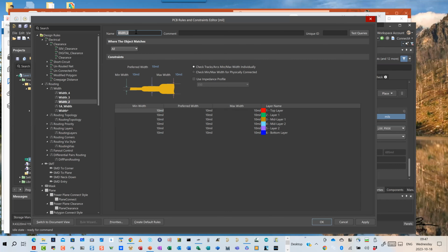That's what I'm going to do here. Now, you'll see this when you go through the groups. There is actually a 5 amp class in there that I created. This one's going to be my net class 5 amp. And again, 5 here. Now, be careful here. You might get some red text. Your minimum must be less than preferred and max, and preferred must be less than max.